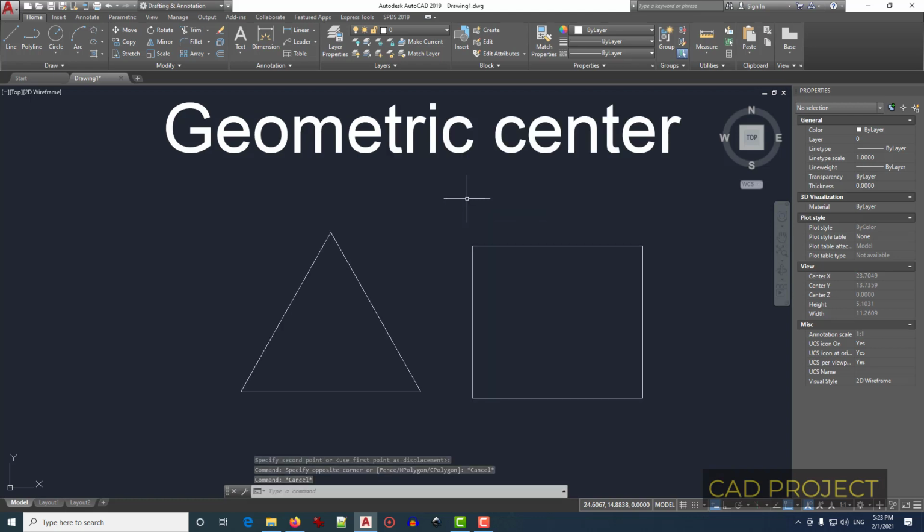The next one is geometric center, and it refers to other geometrical shapes that are not rounded. In order to do that, once more, type L, press enter, and we come close to the edge of this rectangle and it points me to the center of this rectangle.